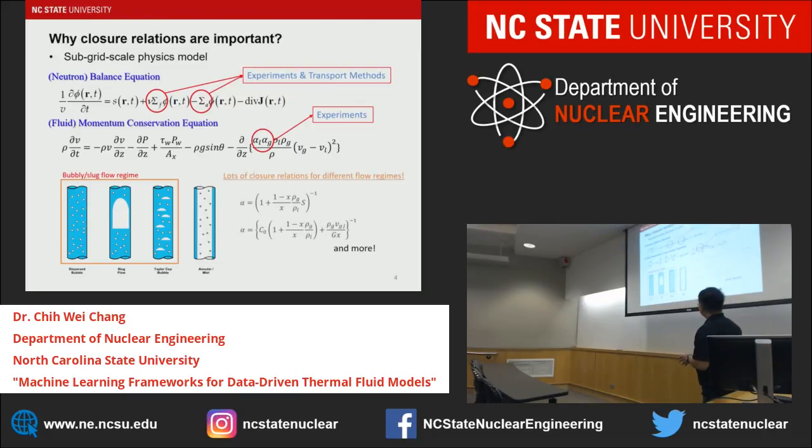And in each flow regime, we probably will have a different model to best fit the data in that specific regime. And the model parameters need to be adjusted, because with changes of geometry, pressure, or mass flow rate, the parameters need to be adjusted to allow the model to capture the data.